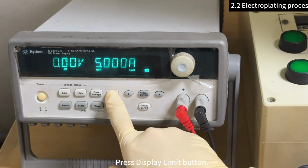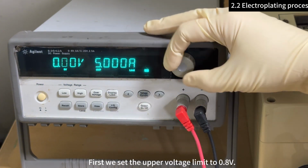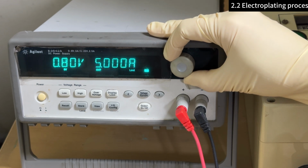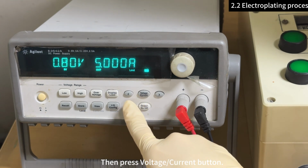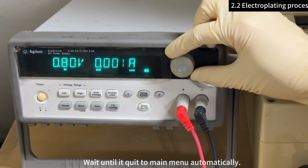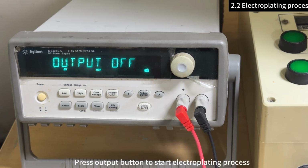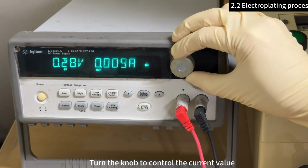Press the Display Limit button. First, we set the upper voltage limit to 0.8 volt. Then press the Voltage Current button. Set the upper current limit to 0.001 ampere. Wait until it quits to the main menu automatically. Press the Output button to start the electroplating process. Turn the knob to control the current value.